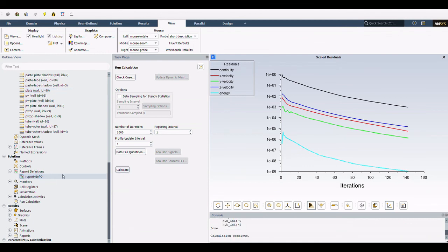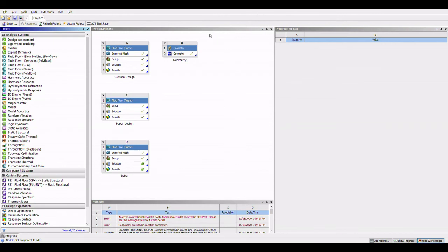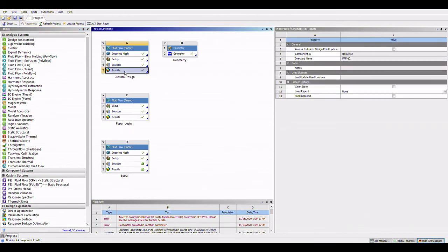Now we can calculate the temperatures in report definition. From the report definitions, we find the temperatures for outlet and the PV top average: 310.77 and 311.25. Now the solution is all done. Now we have to go back to CFD post processing. After we're done with the solution, now we can go to results, opening results.